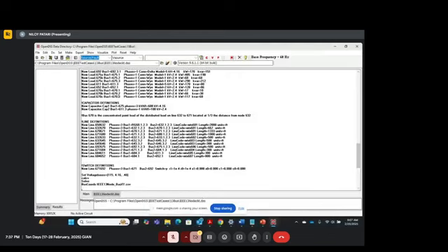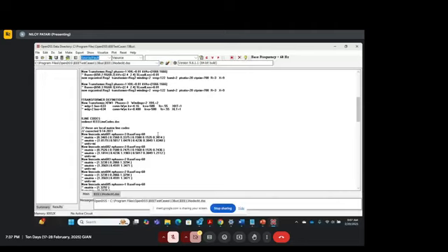So here I was talking about the line, because why don't you need the redirect? Because if you see the line definitions here, it is this line connected between 650, connecting between RG60 to 632, and then it also shows the line code, which is MTX601, right? The MTX601 is already explained. MTX601 is already shown here. So you don't need this line codes.dss, but if you have it, it doesn't make any change, because whenever OpenDSS runs the program, it will definitely go into this particular configuration, which is MTX601.